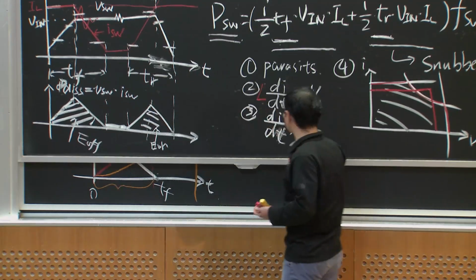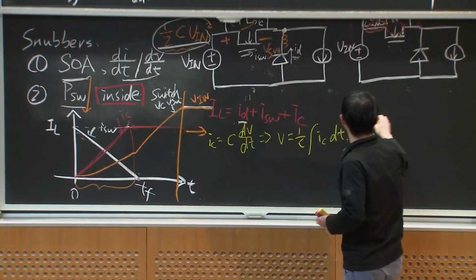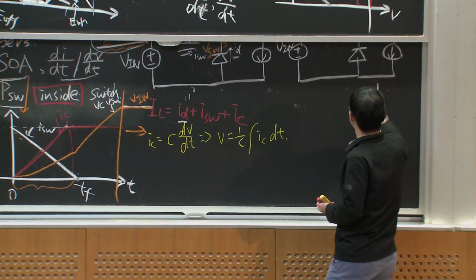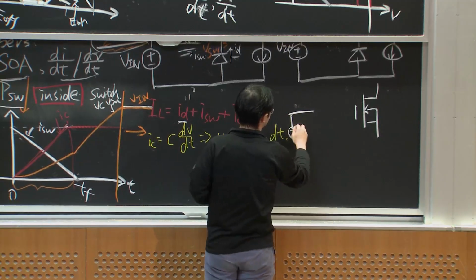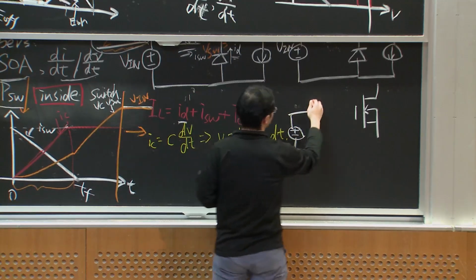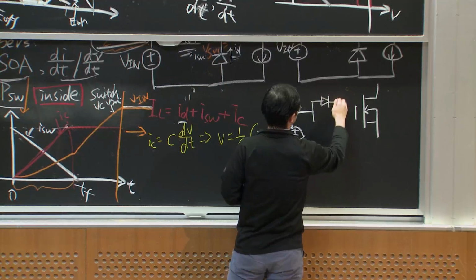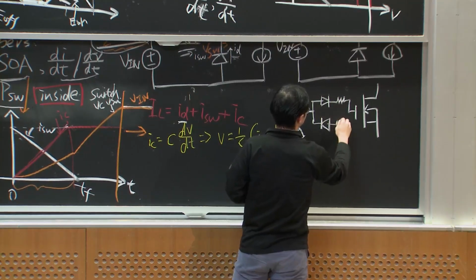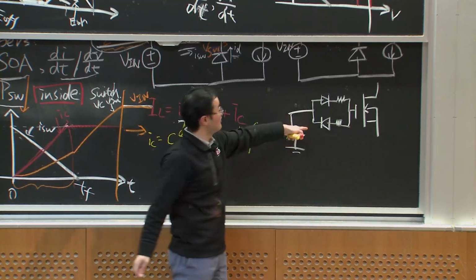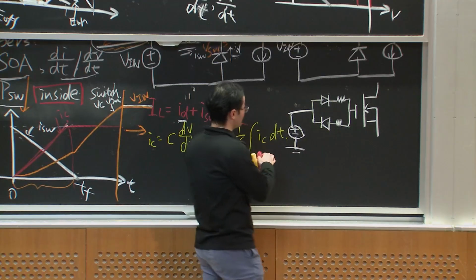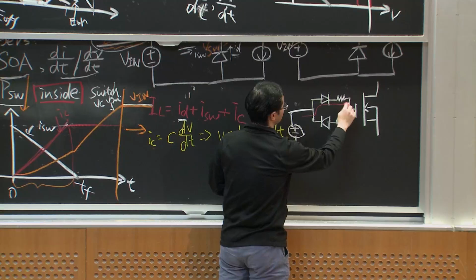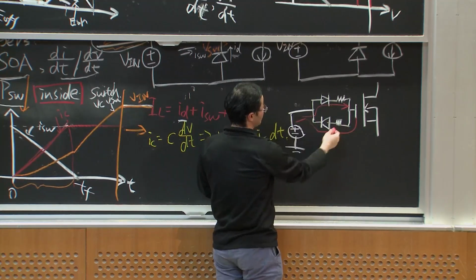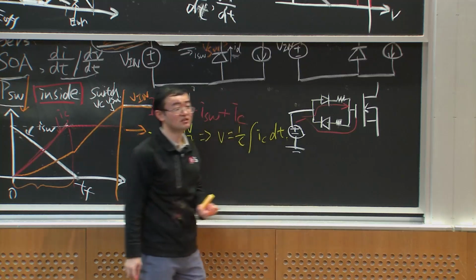So I want to introduce a small bit of the gate drive, for when we want to drive a MOSFET. This is the voltage source, which is the gate drive, and we can have different paths for the turn on and turn off of the MOSFET. During the turn on, we can select a relatively big resistor to charge this capacitor. For turn off, we usually want it to be fast, so we can have a small resistor here.